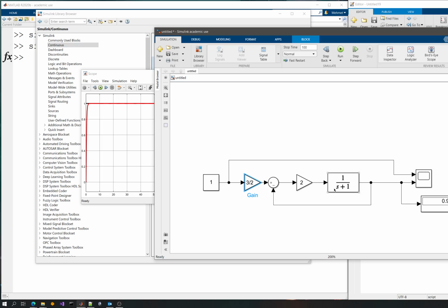So 2 divided by s plus 3, plugging in and using the final value theorem, you can see that it is 2 divided by 3. By using the inverse of that gain as a DC gain for your reference, or as a pre-filter for your reference, you can get almost 1, because there is a division error, numerical errors. You have 0.9999, which is